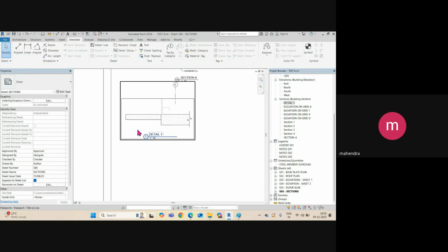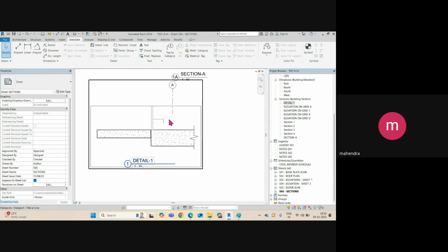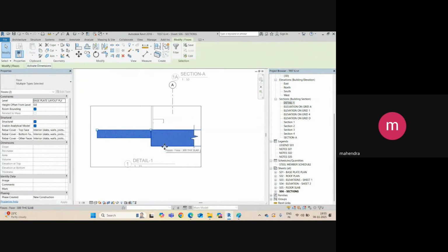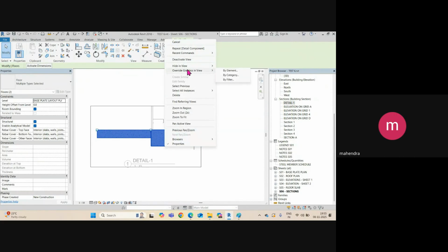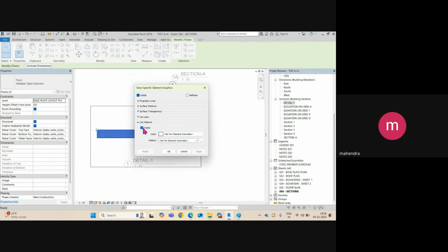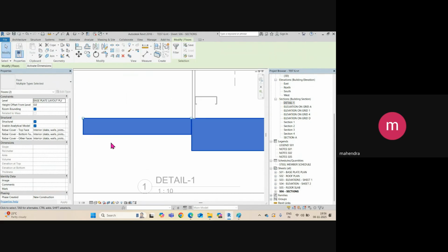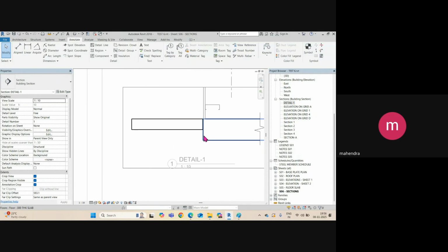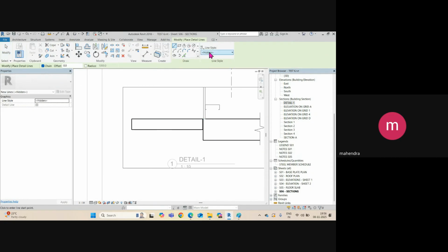scale. And then I want to add the reinforcement here. Okay, so double click. So if you add the reinforcement, you don't need to show any hatch, so just remove this hatch. Go here by element and cut pattern and visible, untick for visible, and say apply and okay. Okay, I want to add the reinforcement here. So type DL. So if you have reinforcement lines here, so you can use, otherwise you can create.